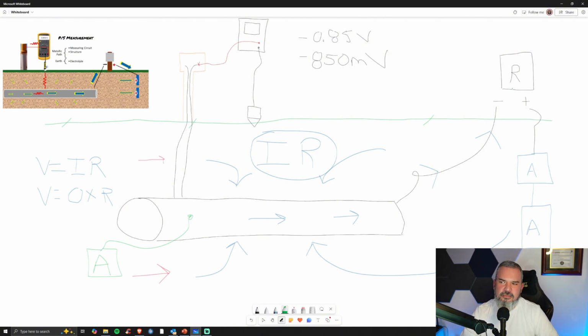Well, as soon as I turn my blue current off and even my friend's red current, what's going to happen to these green anodes? They may produce green current. Yikes. So that means that my instant off is no longer off again. I did not consider the voltage drops in the earth.